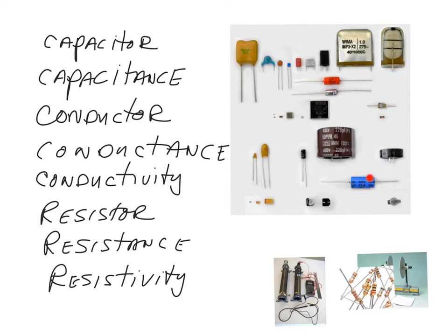And the rolled-up type devices are the older models of capacitance, and they're basically two pieces of conducting foil with a dielectric, like a piece of plastic between them, rolled up. So if you cut this open, it would unroll into two long pieces of foil with a dielectric between it,